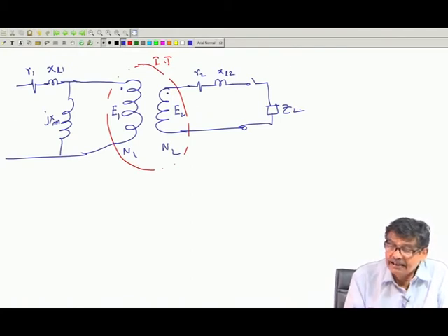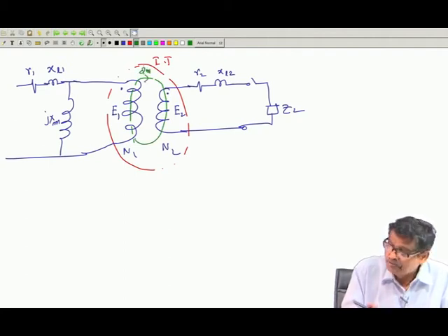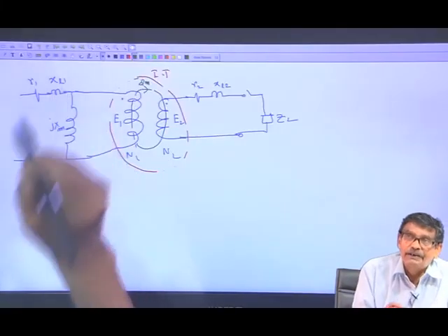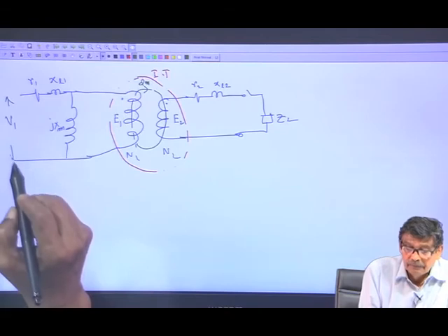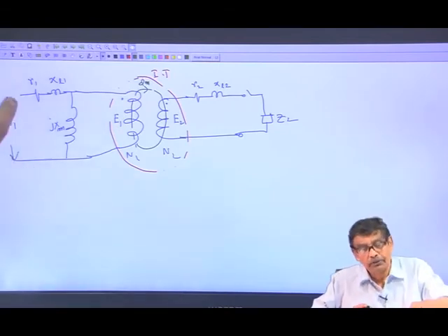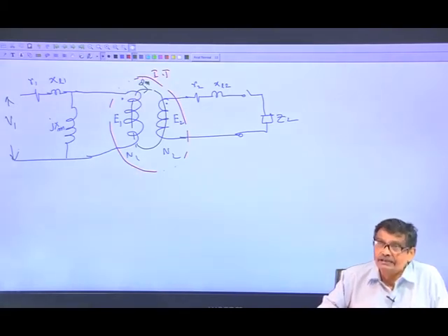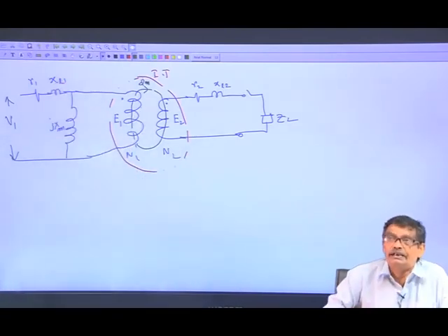Therefore, this is the ideal transformer, where all the fluxes are mutual, mind you. Here is the mutual flux phi m plus the leakage flux phi L 1, and N 1 d phi L 1 dt is shown as a drop here, because this is your supply voltage. Out of this total supply voltage, a portion will be dropped in R 1, no doubt, and there will be another small voltage drop because of leakage flux, which is not going to create your magnetizing current. That voltage is consumed by the leakage flux.